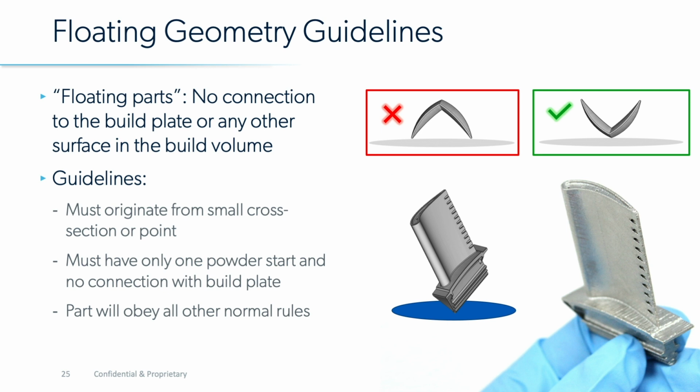One really powerful factor about this is you can stack parts on top of each other or next to each other, nested and overlapped in Z height. And where the business cases really get strong here is where you can, compared to attaching to the build plate, increase your average cross-sectional area per layer. And in general, when you do that in Metal AM, it increases the efficiency of your build and makes for a better business case.